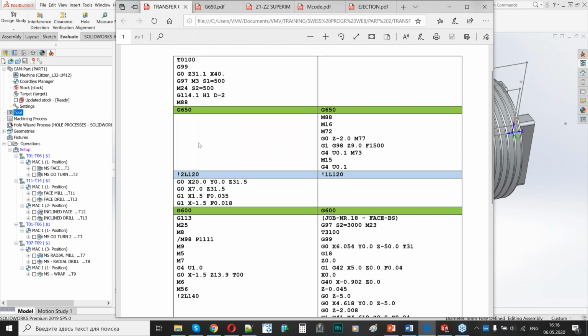So let me quickly explain what's inside of this program. We will perform the first block inside the software. What we're going to do, we should choose the tool, which will be the cutoff tool. Then we should pull out the part from the main spindle. This will be the distance for the cutoff. This is the position of the cutoff tool.